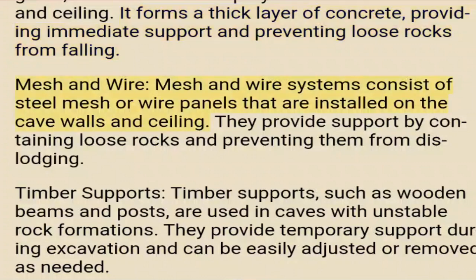Mesh and wire. Mesh and wire systems consist of steel mesh or wire panels that are installed on the cave walls and ceiling. They provide support by containing loose rocks and preventing them from dislodging. Timber supports. Timber supports, such as wooden beams and posts, are used in caves with unstable rock formations. They provide temporary support during excavation and can be easily adjusted or removed as needed.